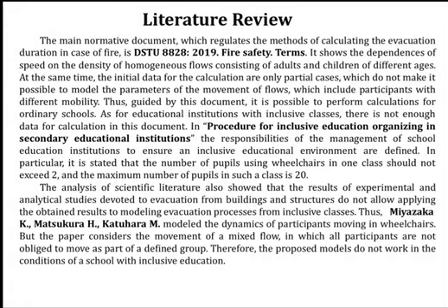Our main documents which regulate the method of calculating the evacuation duration do not allow us to perform such calculations now. The initial data for the calculation cover only partial cases. It allows us to perform calculation for ordinary schools where there are no participants with special needs in the evacuation flow. As for educational institutions with inclusive classes, there is not enough data for calculation in this document.